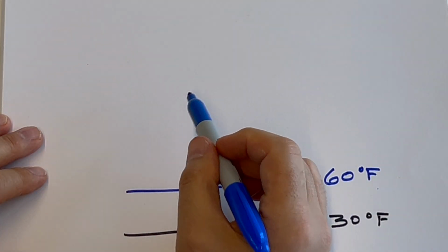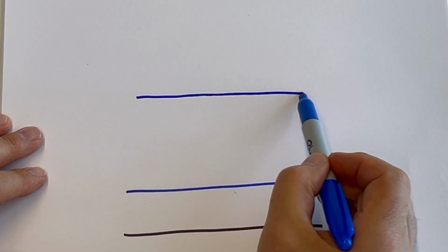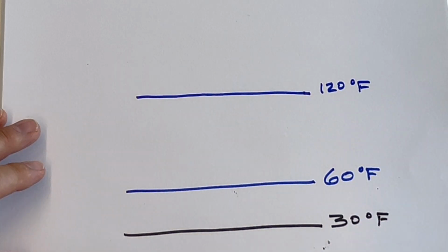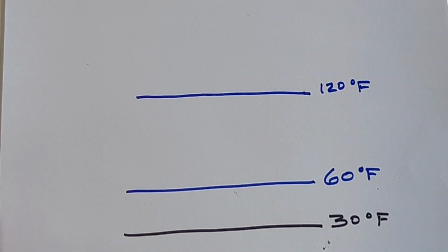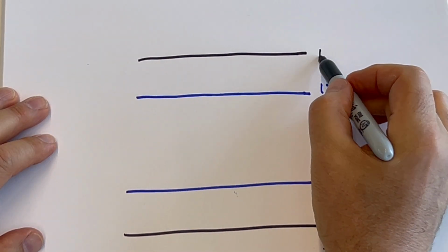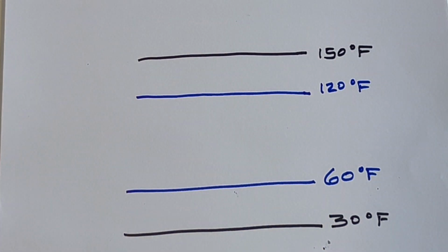And we're heating hot water. Well, if that hot water is at 120 degrees, we use our rule of thumb, and the refrigerant that is heating that hot water will be 30 degrees hotter than that, and it's at 150 degrees.